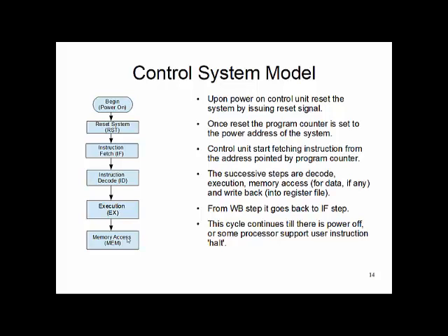If there is something to be done with the memory, then only will the processor send the request to the memory. And then once this is done, comes something called write back, when some result, either coming from the ALU or from a memory read, goes back and is written into the register file.